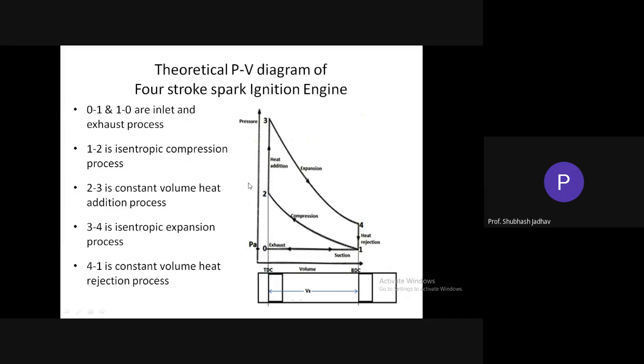So instantaneously the pressure is increasing due to the combustion process. We denote the increase in pressure by moving upward, correct? So here we have moved in the upper direction until the pressure is maximum. Here we say maximum pressure has been reached, and due to what? Due to combustion. Theoretically we call it a heat addition process.